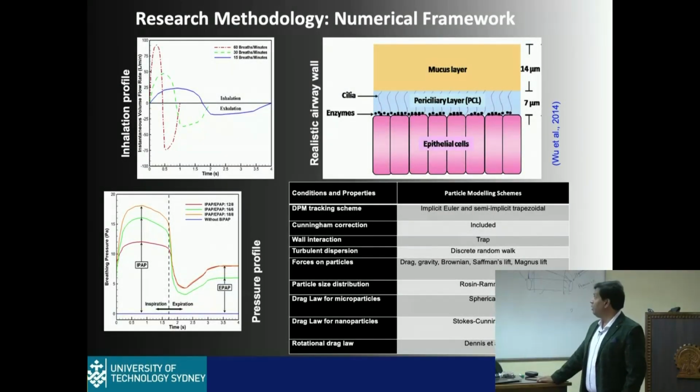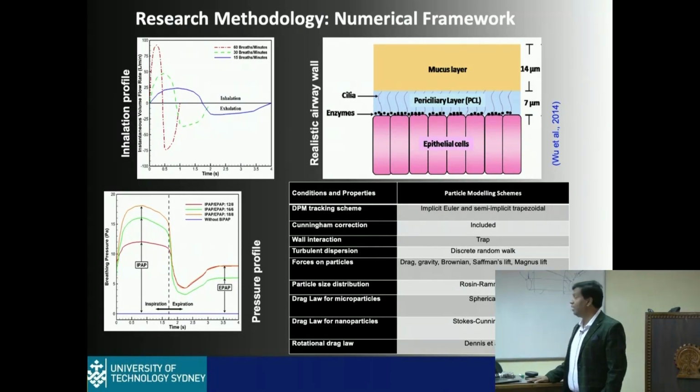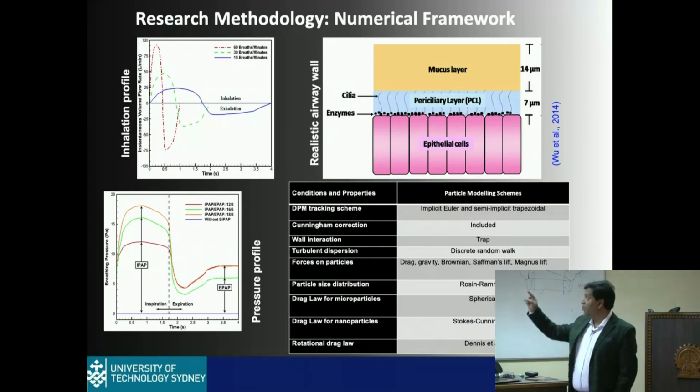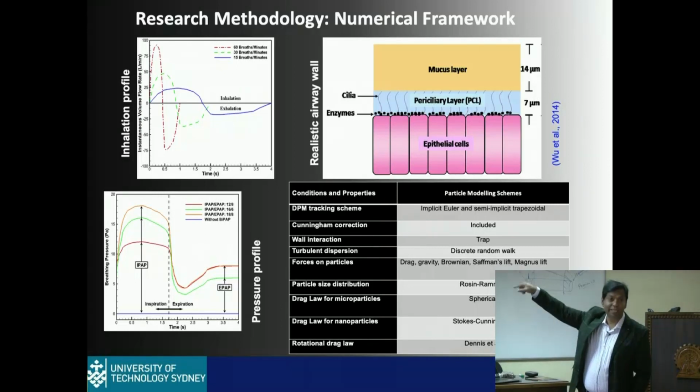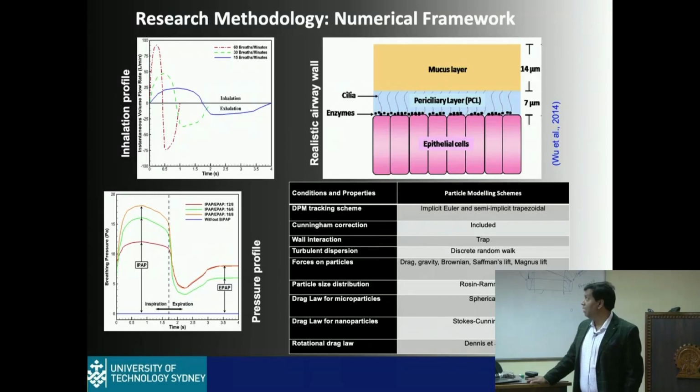So here we applied some realistic breathing pattern we got from the experiment from the hospital. So what is the profile of this breathing? Actually it was like some discrete data, the one that the TA showed you last time, and then from there we drew the profile and we just got some mathematical equations, and then we wrote the UDF. But there is some other way that he showed you how to use the discrete data as a boundary condition.